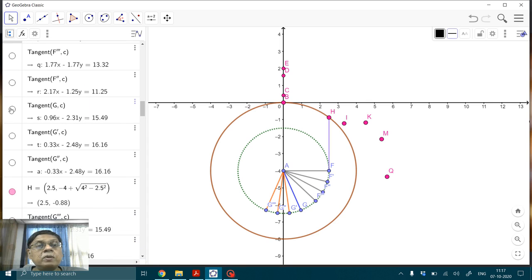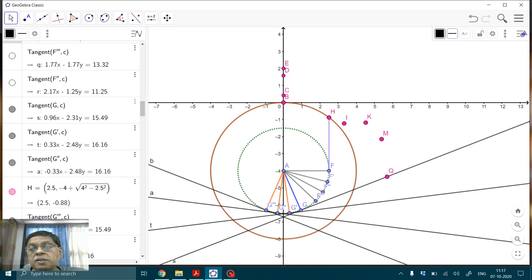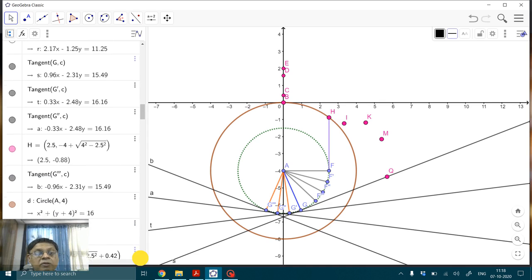Okay. Now we have a tangent. We'll start with this tangent. Then we have a tangent G prime, which is 15 degrees from this dwell position. Then 30 degrees, and then of course the final one, which is the last 112.5 degrees. So you have these tangents. We follow the same logic from each of these tangential points. We look at this position, and then we draw accordingly how much it moves from this point FH, what is the height by which it moves. So we draw from there.